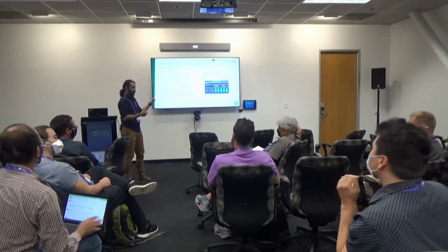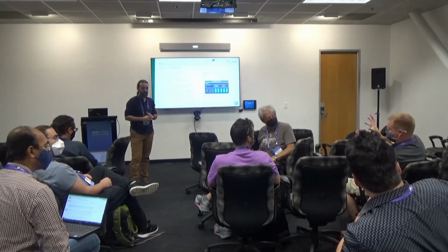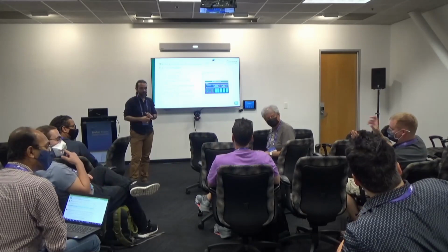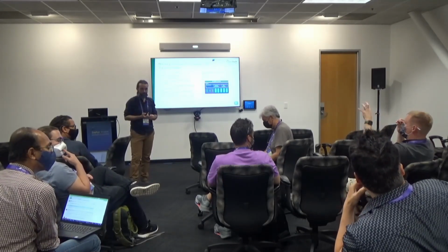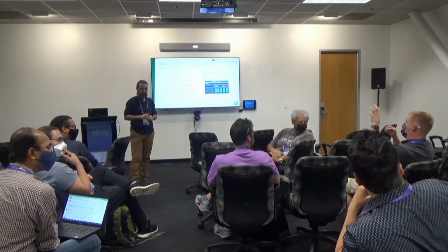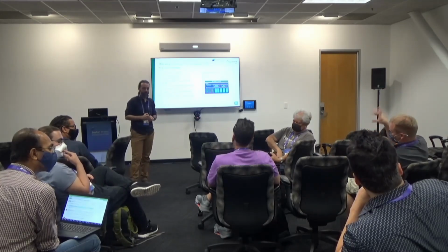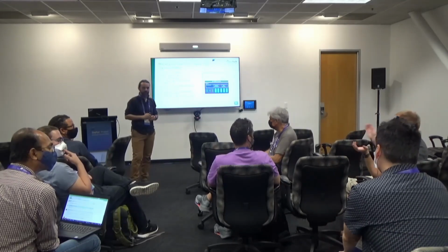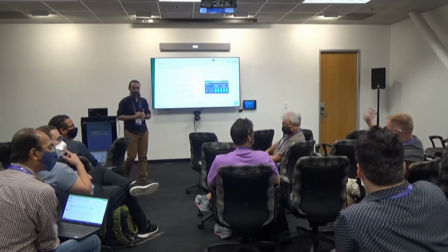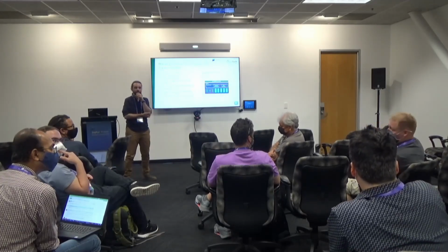Think of this as a platform where I have a layer on top. You can submit libraries, chunks of code to PlatformIO, say it's compatible with this microcontroller. They have targets, I forget their wording, which is the hardware, and then platforms. And Zephyr is a supported platform in PlatformIO, so that's true. And then you tag all this stuff, and it pulls it all for you. So now you don't have to do any code checkout; it does it for you. No. So it's literally like clicking two buttons, and you compile the code, flash it.